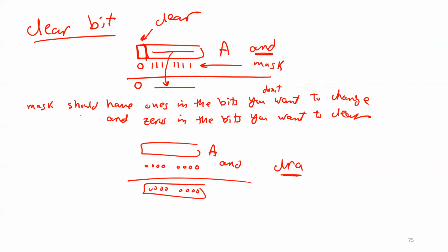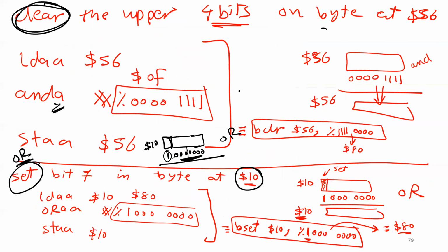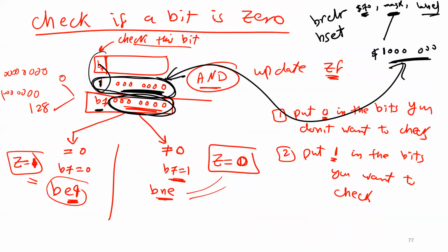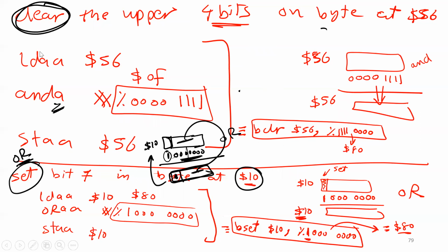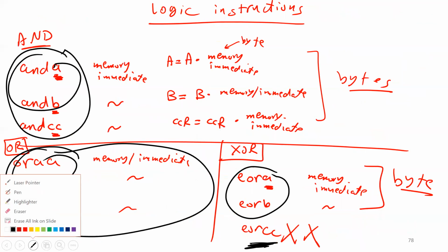Anyway, after that, I have to do an OR operation. So the byte I'm going to get here is exactly the same bits, but I have 1 here, okay? And then I have to store it in this memory location. Again, I cannot do this instruction this way because I don't have an instruction to do an OR operation for a memory location and an immediate value. It has to be through a register, okay? Because these are all the instructions we have right here. So that's why the way I did it is